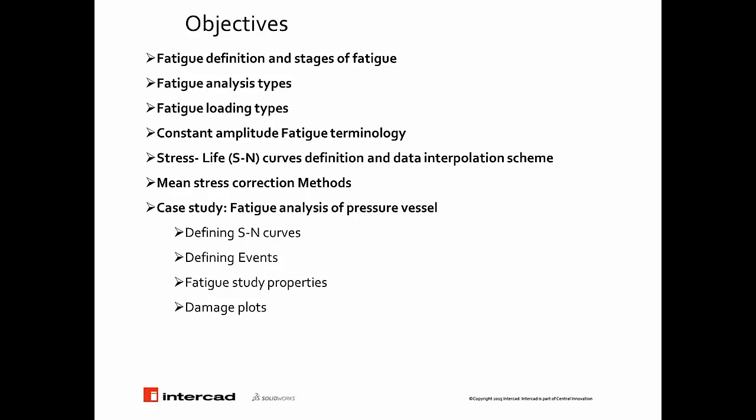studies, which is called stress-life or SN curves definition, how we get the data and the interpolation schemes. We will emphasize mean stress correction methods available in SolidWorks Simulation, and then we accomplish our session with a case study, which is a fatigue analysis of a pressure vessel. We will go over how we define SN curves, how we define events in a fatigue study, and also study properties. And in the results section, we will review the damage plots.